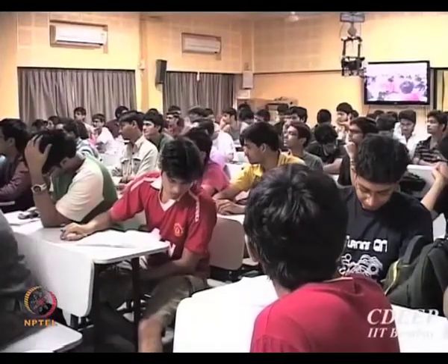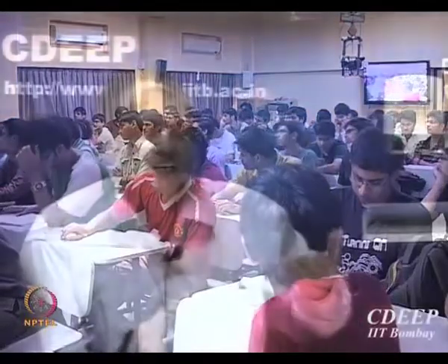Is that correct? So if that is as I say, ROs will get cancelled, not necessarily removed. If RO is not very high, in which case the parallel combination must be taken care of. But as I told you, GMs will be of the order of 10^-2, 10^-3 amp per volt, whereas ROs will be of the order of 10^6, 10^7 ohm.